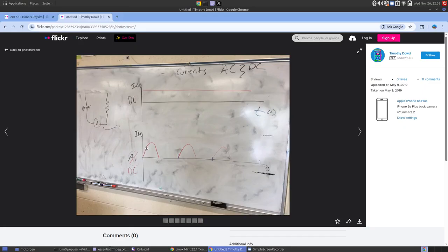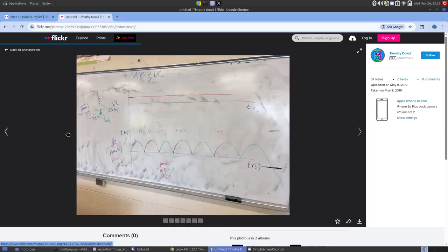It's got an increasing to a max and then decreasing back to 0. It's got a time when it's off. It increases to a max and back to 0 again. But all that time, the current's always heading in the same direction. Now, of course, this is a pretty inefficient way to run our generator. It would be amazing if we could get the second half of the cycle back, but somehow inverted. Let's take a look at how a DC generator can do that.